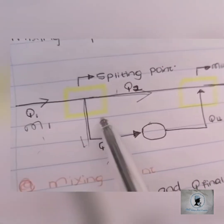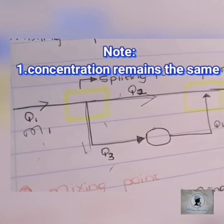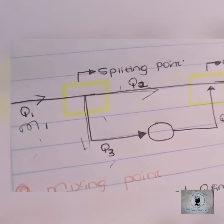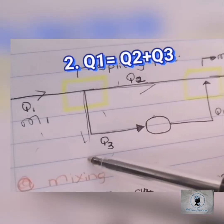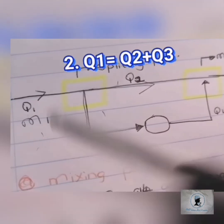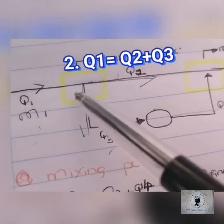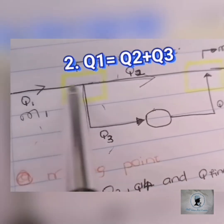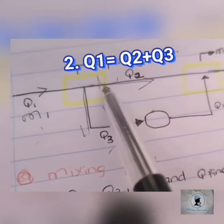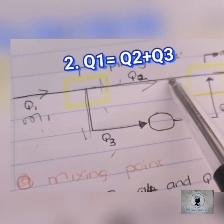At the splitting point, the concentration remains the same, but what changes is the flow rate. Let's say it goes down with a flow rate of 1, and initially it had a flow rate of 10. You're going to say 10 minus 1, which is 9. So after this point, the flow rate of this material will change to 9, right?